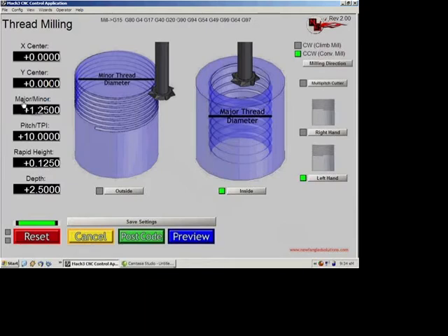It's pretty much the outside of the stock. If the major diameter is what you're cutting to on an internal thread, it's just the outside diameter of the thread, which is normally called out if you had a 1/2-13 bolt or something like that. It would be a 1/2 inch. But the minor diameter is something that's usually not as well published, and you'll have to go to something like the Machinery's Handbook or another resource to try and find that.